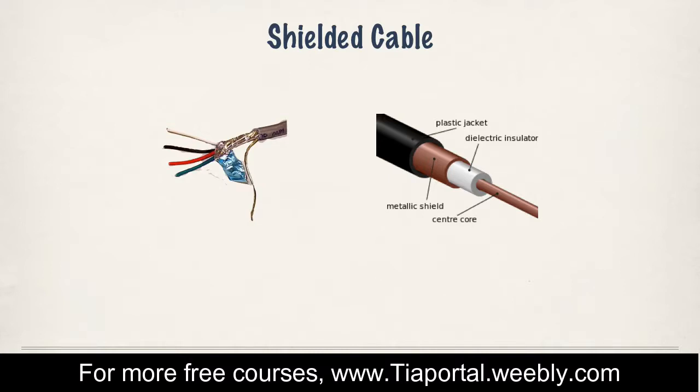Now what we do, though, because we're using cables and connectors in environments where there might be things that would induce interference, where there might be other signals from other electronic devices, signals from, for example, mobile telephones, signals from microwave ovens, a variety of different devices would cause us to have interference and a less pure signal that might result in a fuzzy TV signal or crackly sounds in our audio, in our sound. So we do things called shielding the cable.